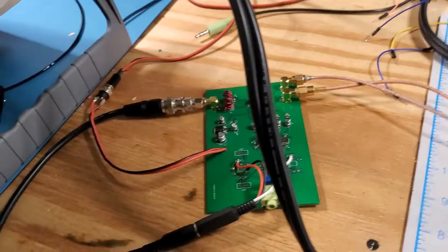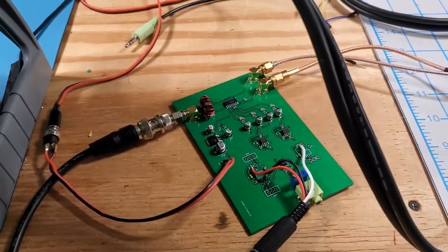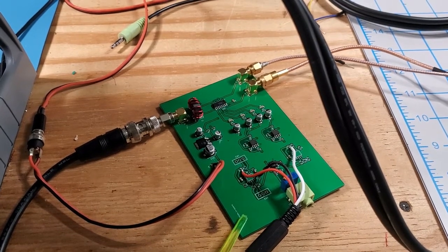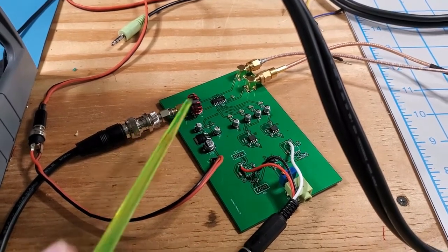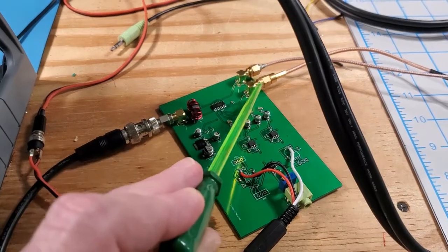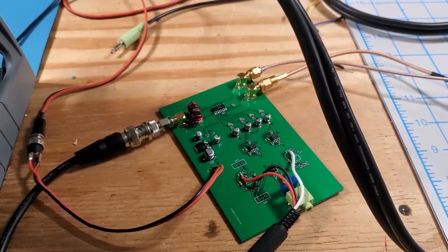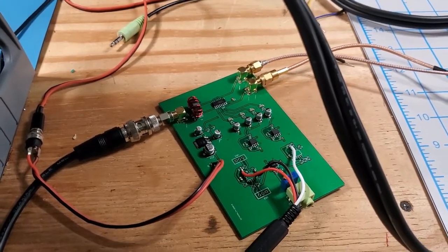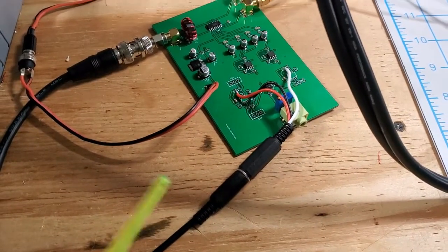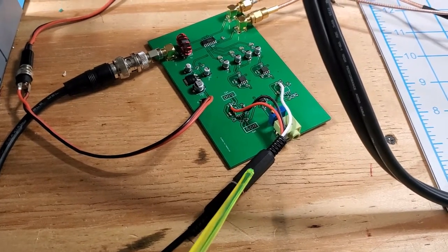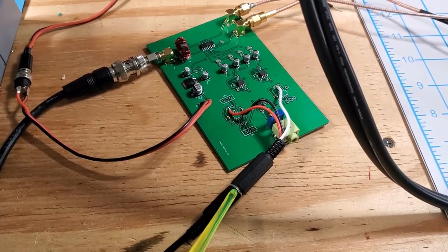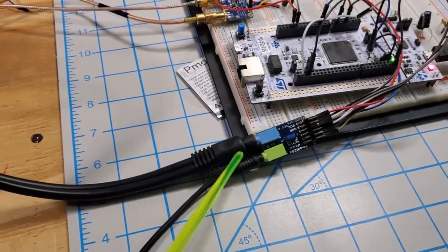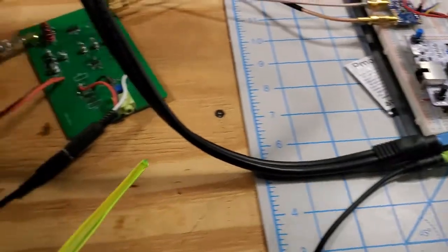And then I've got that hooked up to this board that you've seen before. This is the Tayloe mixer board, my apologies. And you can see here's the two signals, the 0 and 90 degrees RF signals at 7.2 megahertz coming into the board. Here's the stereo audio signal, 0 and 90 degrees offset, coming in from the PMOD board. So this stereo jack here connects to this stereo jack here on the PMOD board.